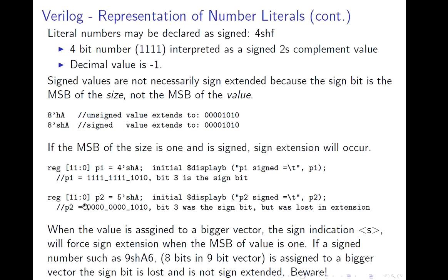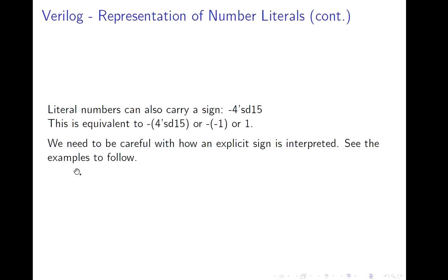So since it indicates 0, it's a positive number. Otherwise, what would have been the number 1010? If I consider only the MSB, which is 1, I would have said this number is negative because it has a value of 1. But that is not the case, because I am representing A as a 5-bit number. First you represent the entire A in a 5-bit pattern and then extend with the number present at the MSB. So this is how your extension occurs with respect to number systems.